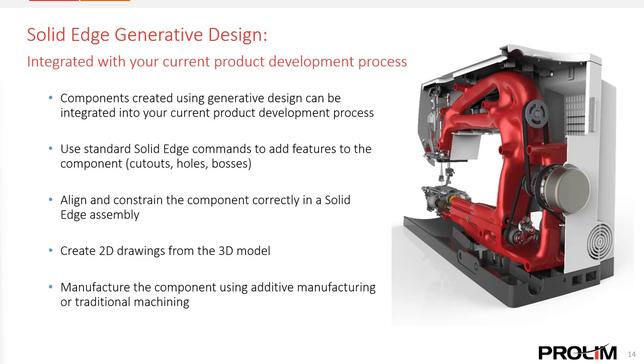A unique aspect of the Solid Edge solution is how easily it enables you to integrate the mesh-based model created by generative design into your product development process. For example, you can use standard Solid Edge commands and add features to the component: cutouts, holes, bosses. You can then align and constrain the components correctly in the Solid Edge assembly. You can create 2D drawings of the 3D models, and you can manufacture the component using additive manufacturing or